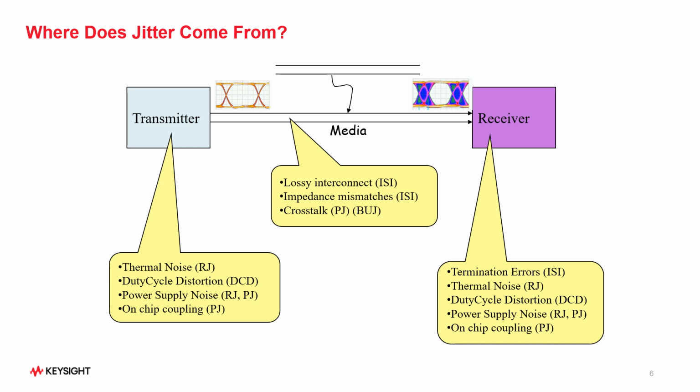Periodic jitter, or PJ, as you see from the slide, can either be uncorrelated or correlated and can be viewed as either being generated by the transmitter circuit or coupled into the transmission line. Whether this source of jitter is correlated or uncorrelated, it is ultimately synchronous to something. Therefore, if one is able to trigger on the various suspect sources, one may be able to eventually track down the source.